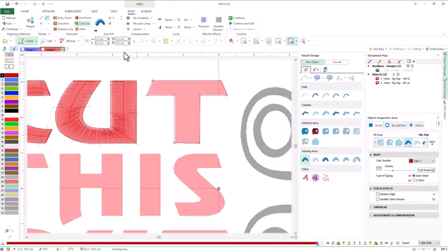And then select cut line. The cut line nodes are always on the contour. By moving the mouse, the system moves them over it. We place a node here. And another one here. The cut line divides the contour in these 2 virtual contours. We add the directions for each of them. The system will generate the stitches almost as if they were 2 different objects.